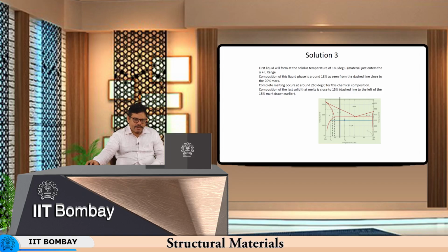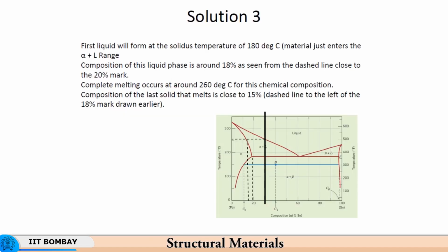But if you take a higher temperature, just at the time of melting, more and more tin gets dissolved, and therefore you have about 18% of tin dissolved in the lead, leading to a greater percentage of tin in the melting alpha. So, as alpha just melts, it has 18% of tin.